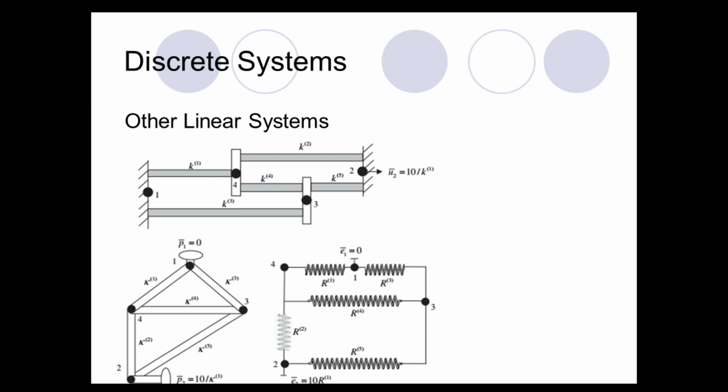We may have much more complicated systems. Of course, in this case, numbering might be important. Now, for example, we have a linear truss system here. So this is my node 1, this is my node 2. So I just give numbers to the essential nodes one by one. It can be either at the top of my vector or at the bottom of my vector, doesn't matter.